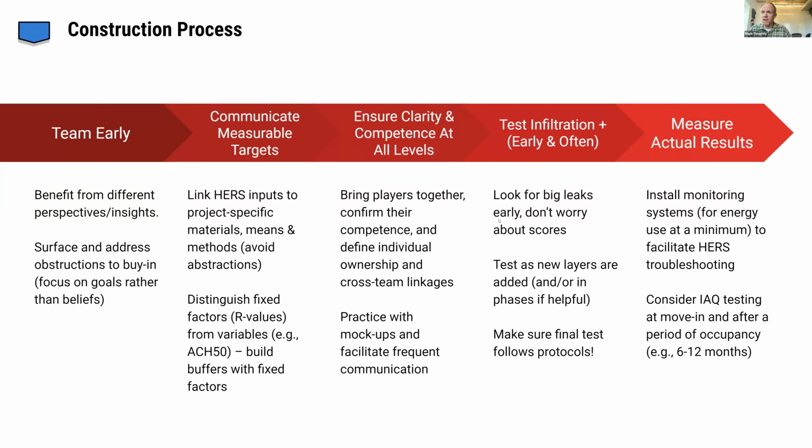And then the final thing, I think, is that we look to measure the actual results. And this is something that's not so much related to the code, but it's related to trying to achieve the outcomes that the code is looking for. We put in energy monitoring systems so that we can see when something starts to go off the tracks. We've had air source heat pump hot water heaters where there's been coolant leaks or refrigerant leaks, and so they switch over to electric boost.